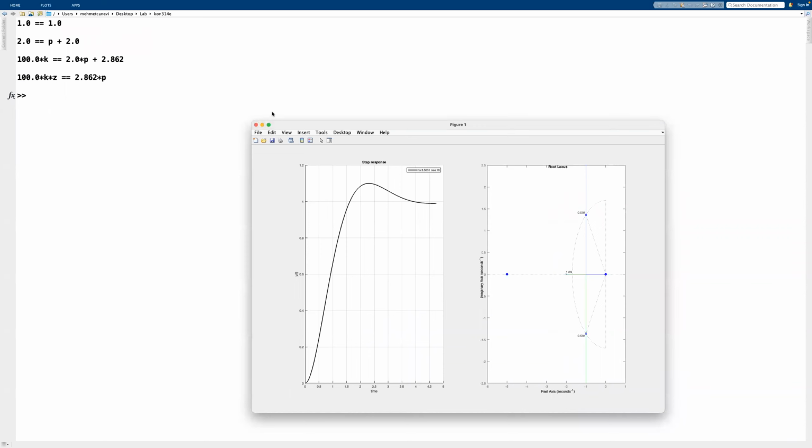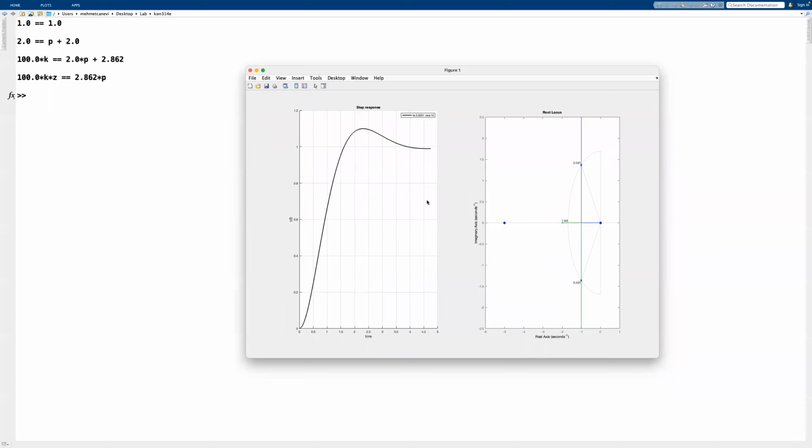Now, interestingly, we did have an issue there. Now we can see that the pole at -5 is canceled out, but there's another cancellation which happens at the origin. So we are actually experiencing a pole 0 cancellation at the origin, which is not quite nice. But you can see what I've talked about earlier.